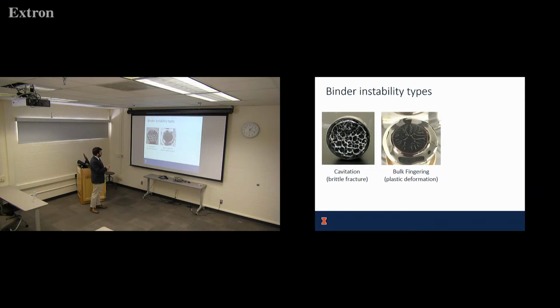Yeah, I cannot see the plate, you're right. Yes, you cannot see the steel plate, right? So you don't see any steel, so you do see binder. But if you look at it under light, you can see also that binder is pretty thin, so it's transparent. But there is binder left, so it's cohesive. So we do verify that it's cohesive in the poker chip test, just to be sure that we're not disadhering from the plate, because we use the exact same testing conditions in that one: temperature, loading rate, aspect ratio, everything.